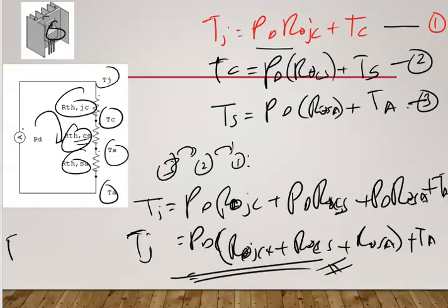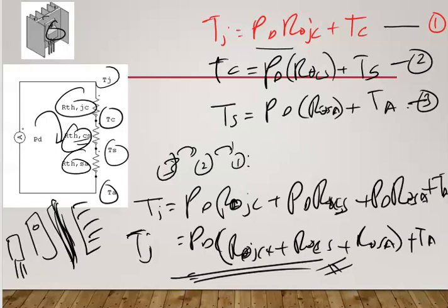So you have your device with 3 legs here, you have your metal tap, you have your washer, not washer actually, what's it called, insulator, then you have your heatsink. So this is your heatsink here. Between heatsink and metal tap they will put some sort of paste, thermal paste.